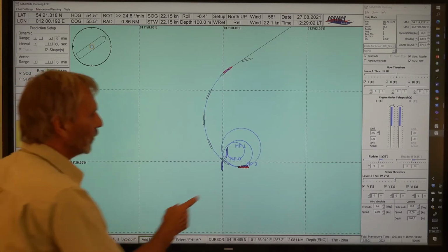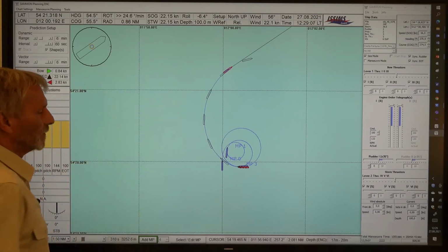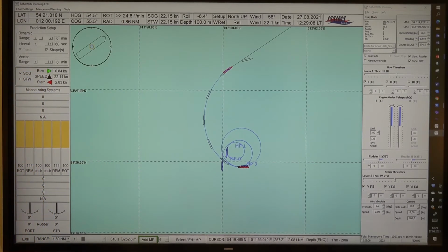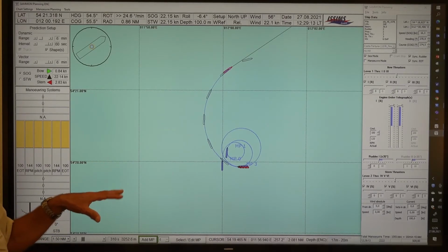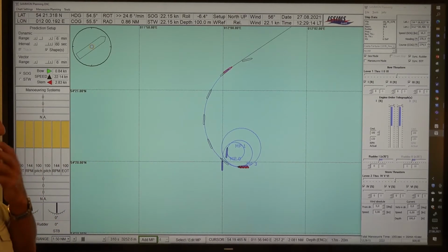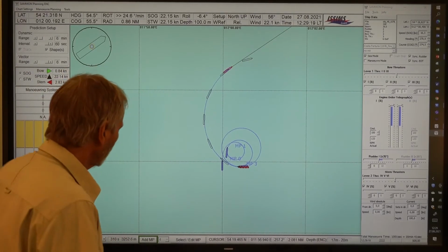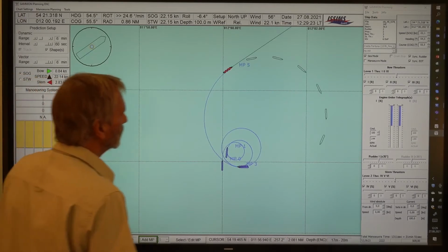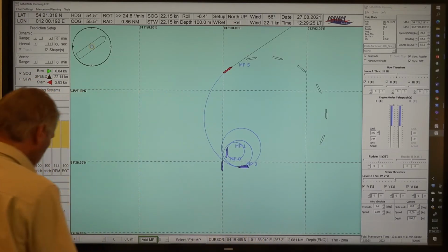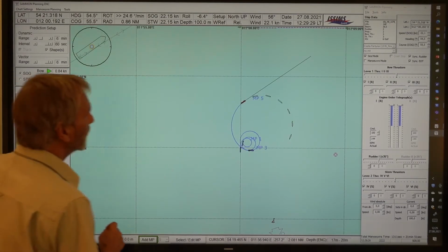And for midship rudder, we have a rate of turn of about 25 degrees per minute. We know this ship is unstable. That's what we have seen in our experiments in the previous movie. So from here, you would go now to other turning. I will enlarge the picture a little bit to allow the full picture.